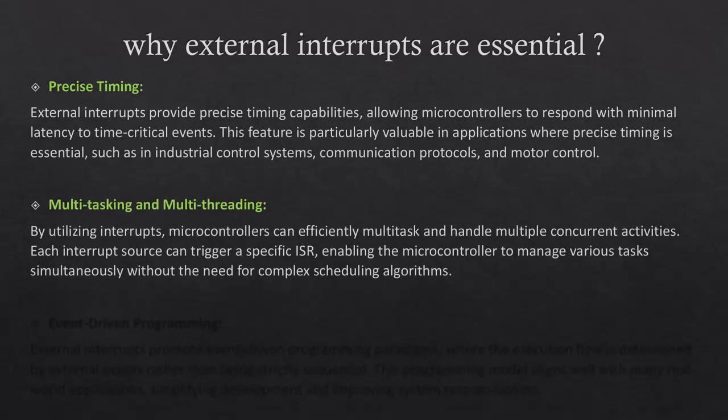Multitasking and multithreading. By utilizing interrupts, microcontrollers can efficiently multitask and handle multiple concurrent activities. Each interrupt source can trigger a specific ISR, enabling the microcontroller to manage various tasks simultaneously without the need for complex scheduling algorithms.